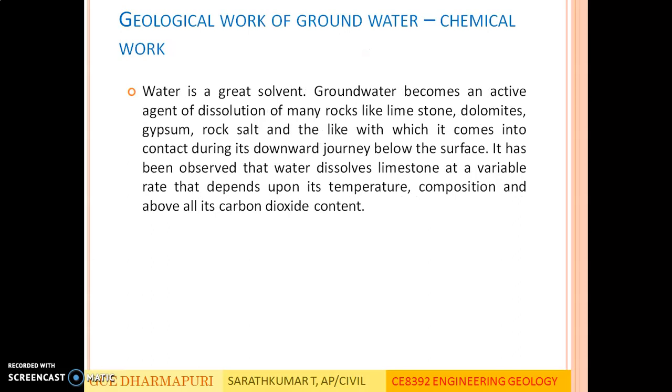Geological work of groundwater: chemical work. Water is a great solvent. Groundwater becomes an active agent of dissolution of many rocks like limestone, dolomites, gypsum, rock salt and the like, with which it comes into contact during its downward journey below the surface. It has been observed that water dissolves limestone at a variable rate that depends upon its temperature, composition and above all its carbon dioxide content.